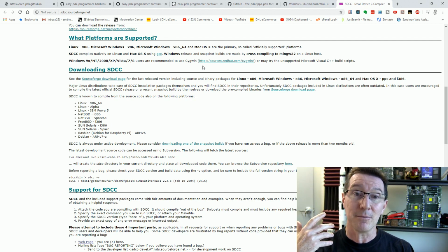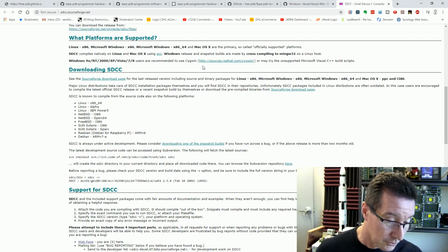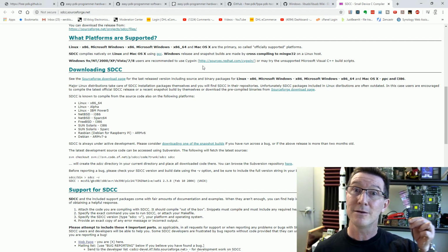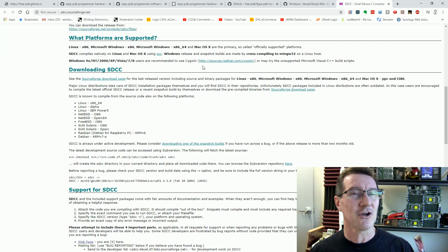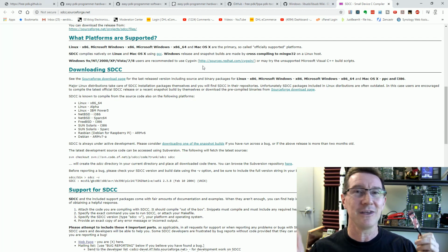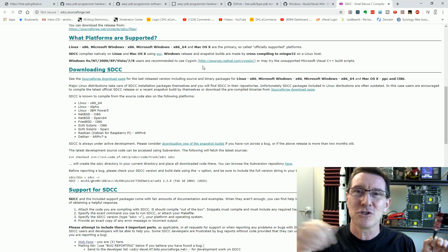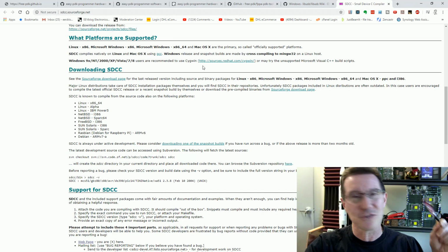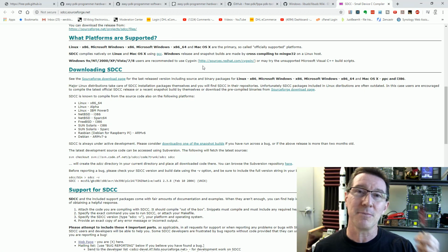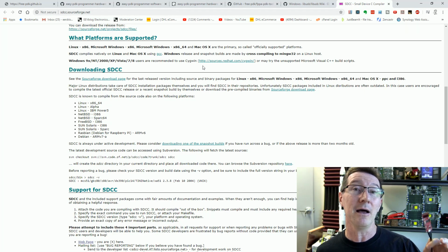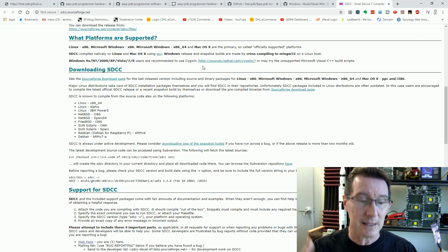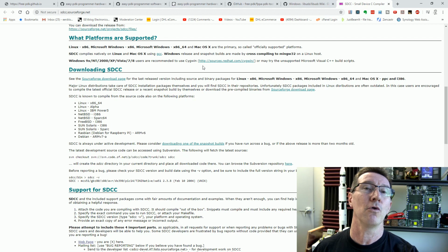and then it will generate a binary file, which we can use our newfangled programmer to program into it. So unfortunately, it's not a seamless automated system like you'd get with your PIC or your AVRs, where it's all under one environment and just seamlessly works, and you push a few menu buttons at the top and it compiles and downloads and does everything for you. This is a bit more tedious, but it could get better over time in terms of integration support, scripting support, and things like that.